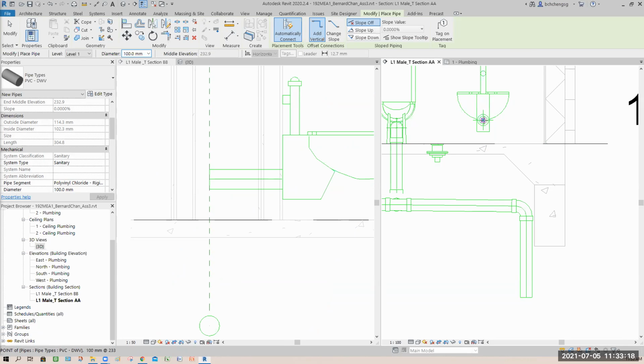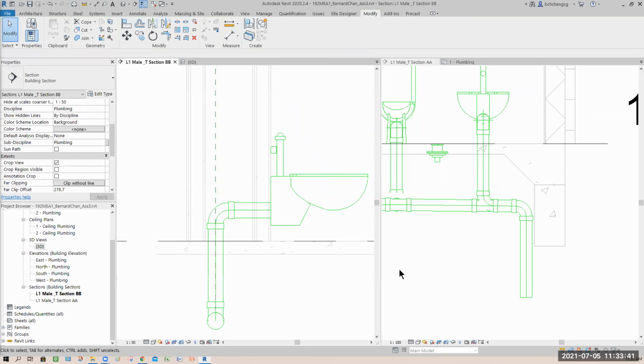Always remember, I said to you before, even in your ducting, correct? Hopefully you can still remember. So snap from here, vertically down, touches the center, like that. Intersection and vertical. So snap it. Now it connects nicely. See? This is what we call your Y joint.